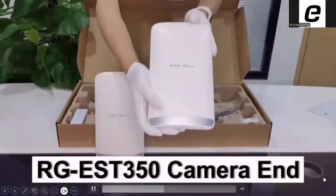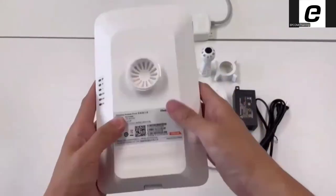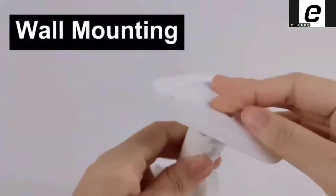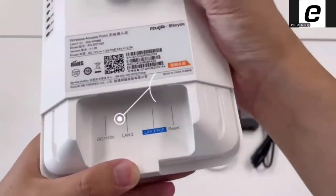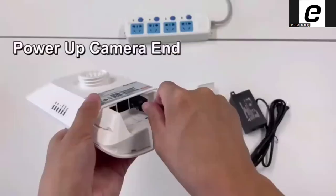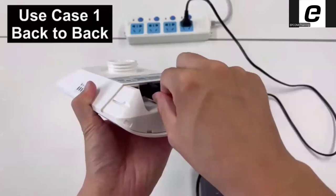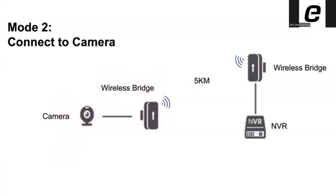And let's see right now the selection, the setup of this RG-EST350-B2 model. This is ideal for projects up to 5 kilometers and with bandwidth of up to 800 megabits per second. It has 2 gigabit LAN ports. For all these models, the PoE adapter is included in the package.